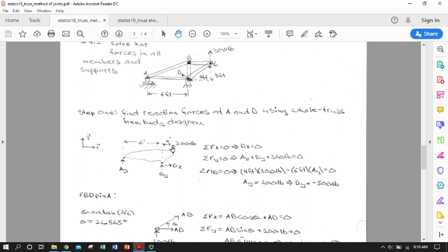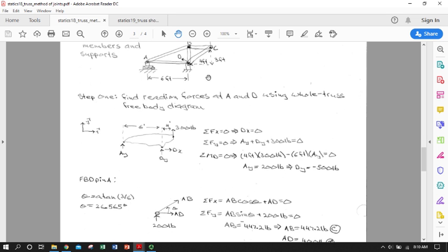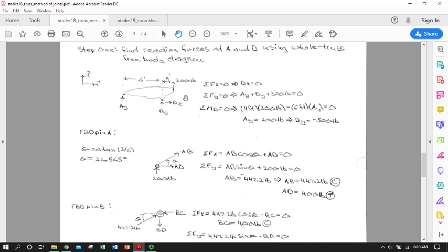But as it turns out, because this 300-pound applied load is only being applied in the vertical, and I'm going to be taking my moments about point D, I have my radius from the point to the applied force, R cross F. So I don't actually need the 3-foot horizontal distance between D and C. Okay, having taken over my forces, known and unknown, and my critical dimensions, I can now apply all 3 of the equations of equilibrium to my whole truss FBD.